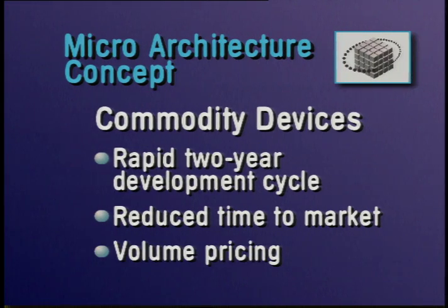For these reasons, even the largest of computer corporations have seen fit to build and support consortia to provide sufficient market presence to pay back the design effort. And of course, these devices benefit from high volume, which allows lower pricing. This counter-argument to embrace an emerging commodity microarchitectural implementation was most persuasive for the CRAY T3D project team. The processor selected was from the Alpha microprocessor family from Digital Equipment Corporation. This device was selected primarily because it best met our objectives of providing high performance and high precision for both floating point and integer data types.